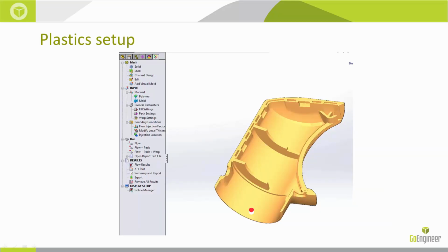As far as the setup goes, SOLIDWORKS Plastics is fairly intuitive in that we're stepping through the process parameters of a manufacturing process. What's different from the last 2 packages that we looked at that were defining environmental loading, this is all manufacturing. Right? So a little different mindset. We'll need to define how long it takes to fill the plastic, what the temperature of the mold is, what's the plastic that we're using, where does it come in.